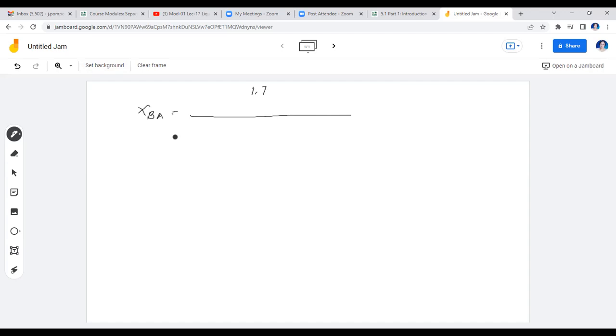Now, to convert it to moles, you need to divide it by the molecular weight of B. In this case, our B is methyl isobutyl ketone, and it has a molecular weight of 100.16. Now here in the denominator, you have already converted the 1.7 mass to moles. You do the same here in the denominator, but this time all three components' number of moles will be placed.